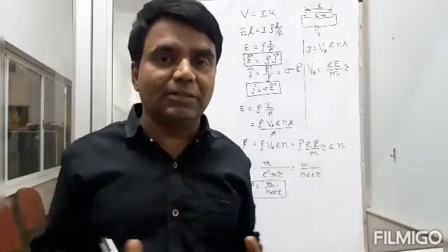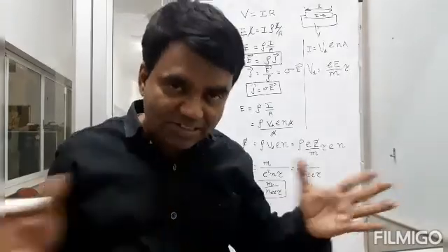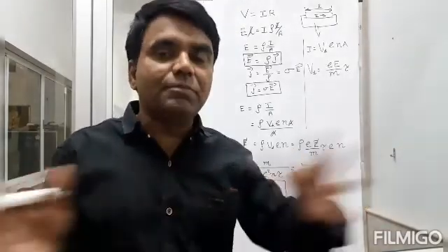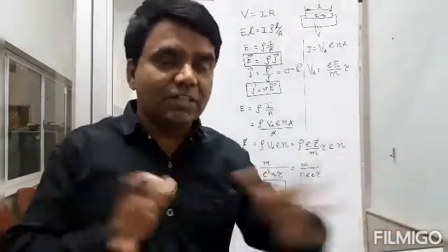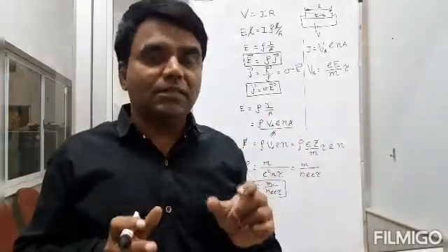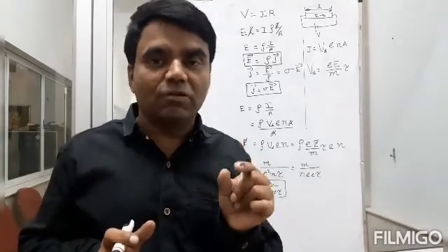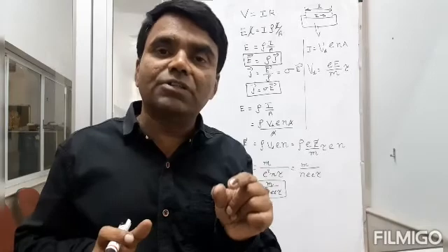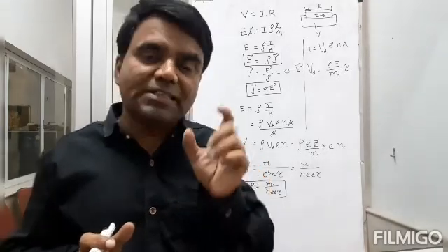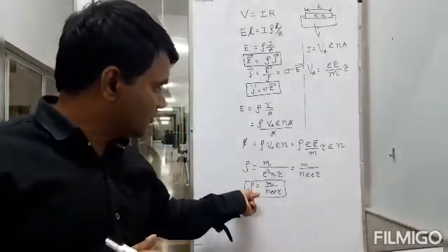When the temperature is high, I hope you understand this, electrons will move fast, and the collisions will be more frequent. When the collisions between the electrons and the atoms are more frequent, the relaxation time is going to be smaller. The time between collisions is going to be smaller. If the time between the collisions is smaller, then resistivity will be higher.